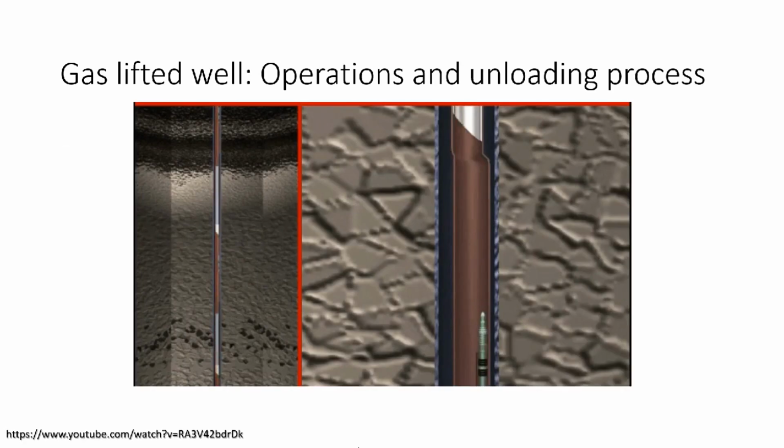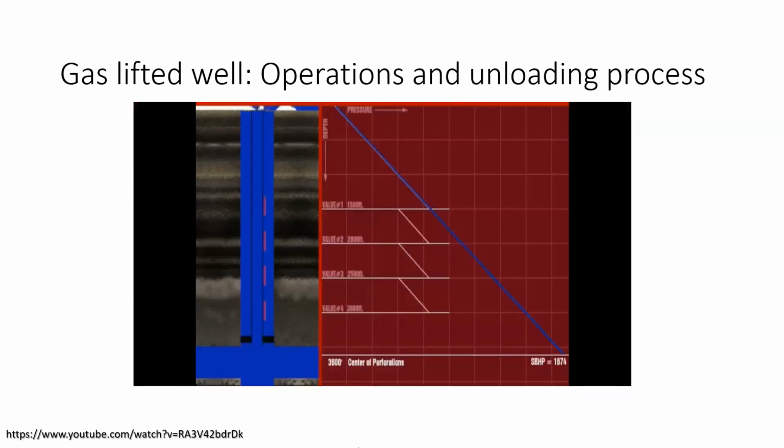During the initial unloading process, casing and tubing pressure gradients in the static loaded condition are equal. All gas lift valves are in the open position from the weight of the hydrostatic fluid in the tubing and casing annulus. As gas is injected down the casing annulus, it displaces the kill fluid through the opened gas lift valves into the tubing string and to the separator or storage tank.